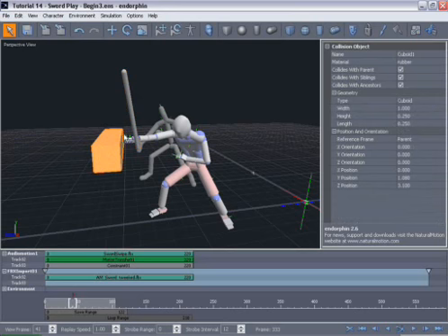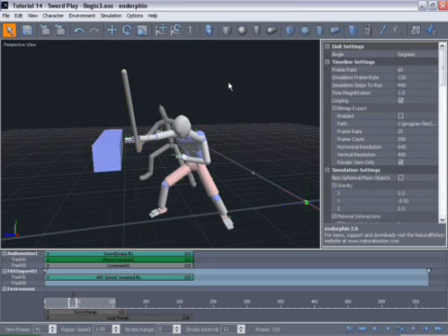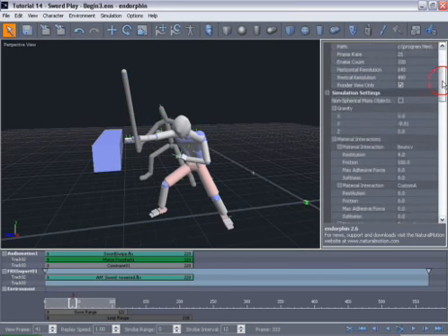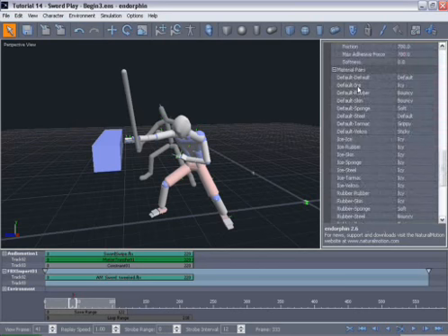And to do that, we can select anywhere in the background of the viewport and move over to the Simulation Settings property view, where we can scroll down until we reach Material Pairs. And this is where we begin to define the way that different material pairs interact with each other. And we're interested in default and rubber materials, and that's currently set to bouncy, which is fine.